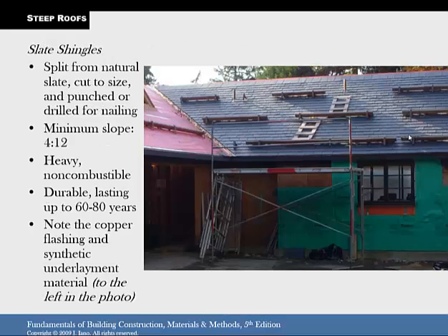You've got slate shingles, which are very expensive and heavy. They can last up to 60 to 80 years, but then you would also have to beef up your structure because of the heaviness of it. So if you're going to be in your house 80 years, I guess it's worth it.